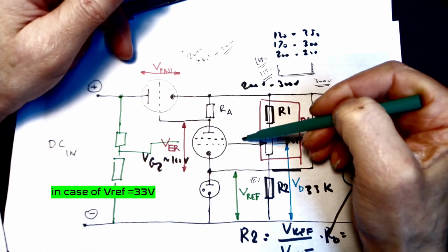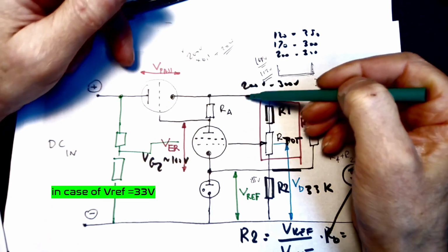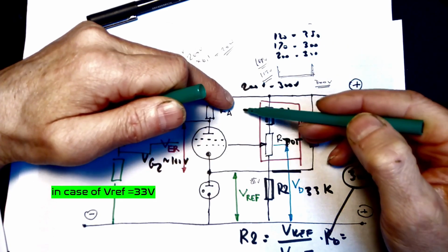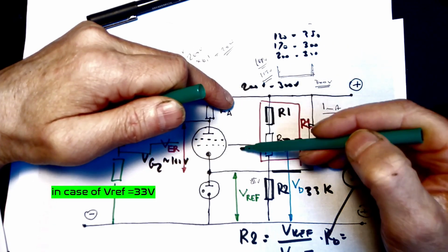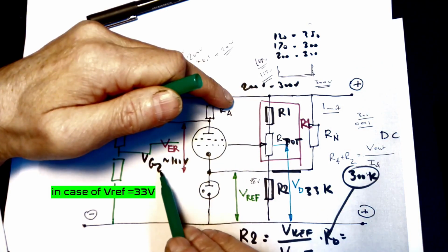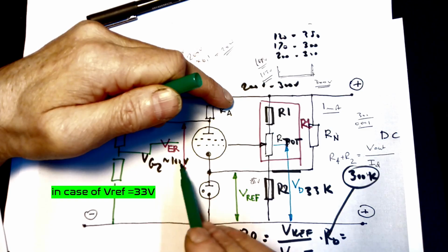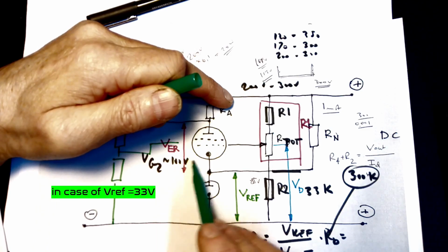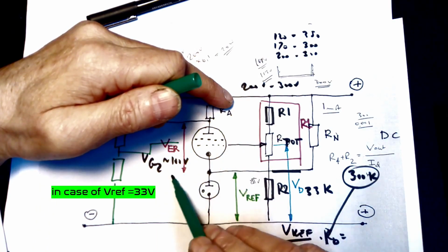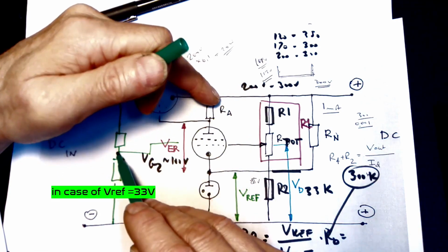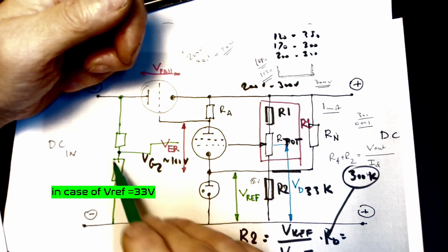But the output side is a problem, because when we lower the output voltage, this voltage goes down. So at one moment it becomes unstable, and even stops working properly. So a much safer way is powering it from the input.